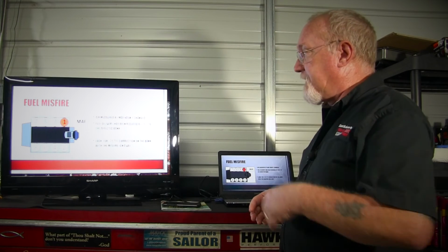So again, no fuel, but now I got a whole lot of unused oxygen. None of that's going to react in the exhaust because there's nothing to react with, right? And this O2 sensor is definitely going to react to a lean condition. And I may see fuel corrections up in the 20s as a result, because I'm essentially 25% short. So that's one thing that you can look for there on the fuel trims. Again, depending on the OEM and the strategy that the ECM uses, as soon as the ECM sees that misfire, it may just go ahead and shut it all off, and you may see the same on both. It's going to make an adjustment. It's going to understand, hey, this ain't happening, go into open loop, and totally throw fuel control out the window